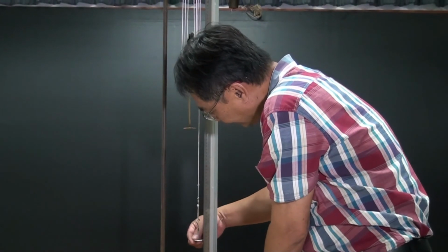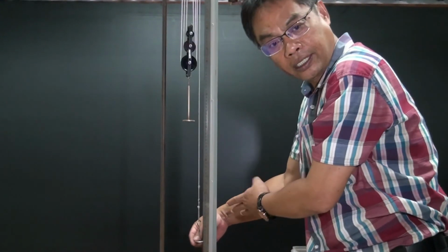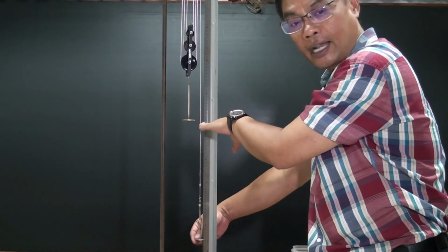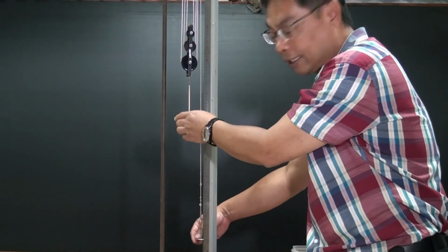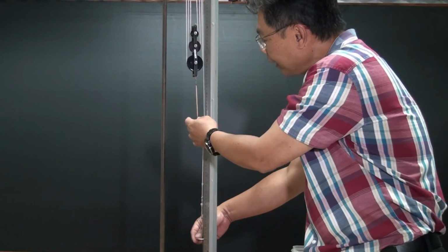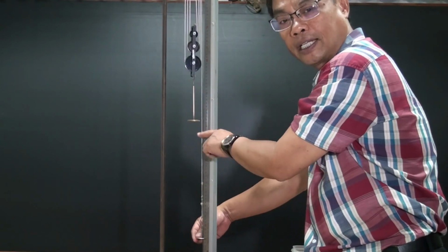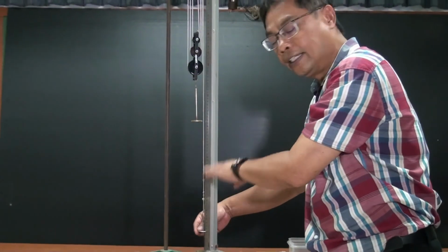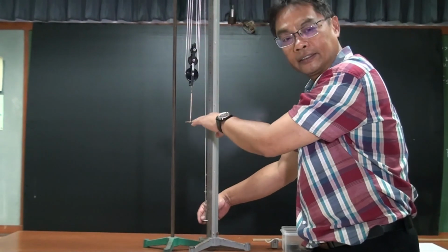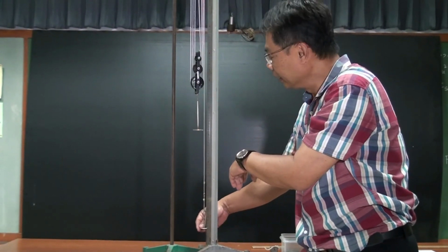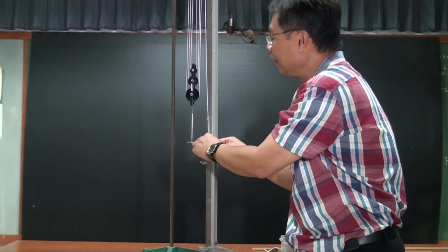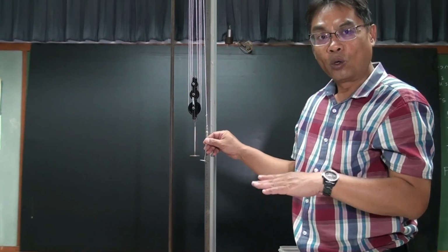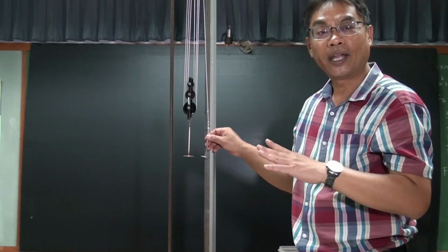Keep in mind that the mass on the right is going to be your force F that you're actually exerting on the system, and the mass on the left is going to be your W, the weight which you're trying to push up. And from there, you could calculate the friction and everything else inside of the system. So again, you want to achieve the kinetic equilibrium by putting the mass in such that once you tap it a little bit, the mass on the left moves up at a constant speed.